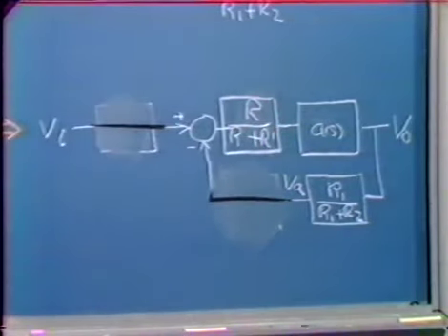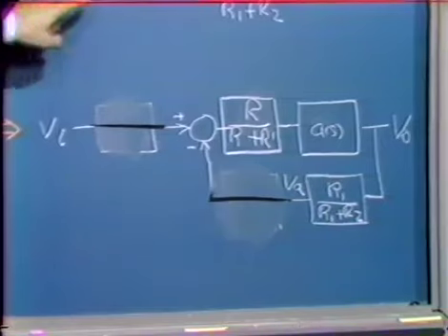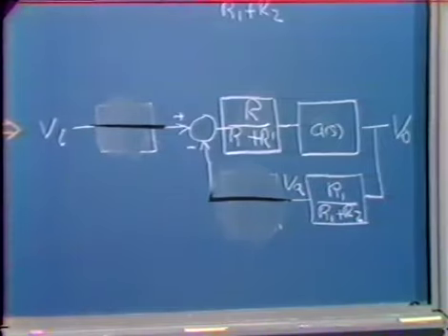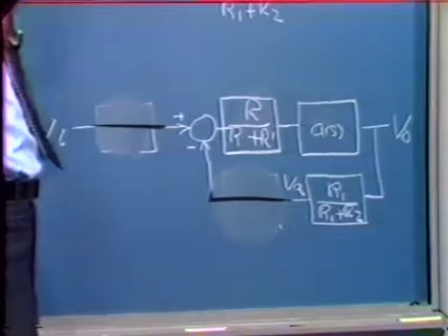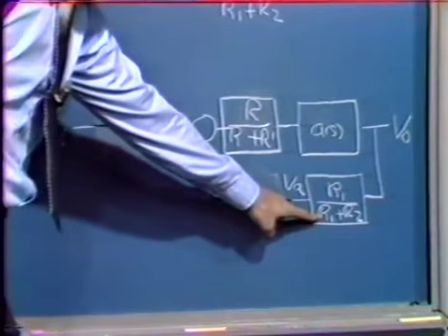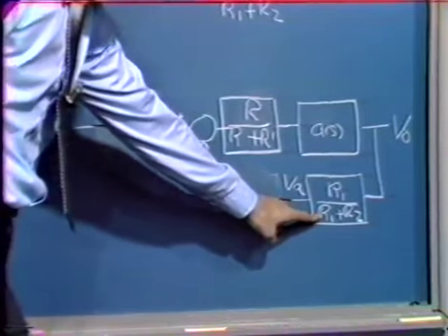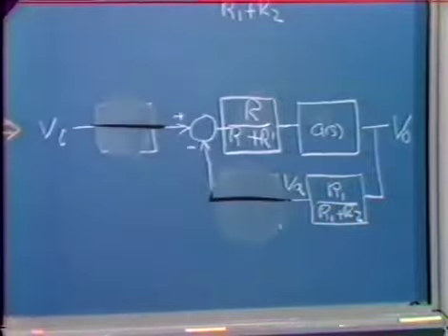Now what we see is we have broken the interdependence between ideal closed loop gain and loop transmission magnitude, because the ideal closed loop gain for this system, assuming large enough loop transmission magnitude, is simply the reciprocal of the feedback path, in particular R1 plus R2 divided by R1. So we haven't changed the ideal closed loop gain.